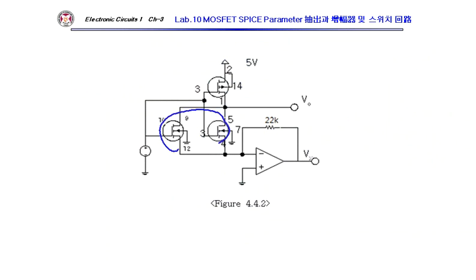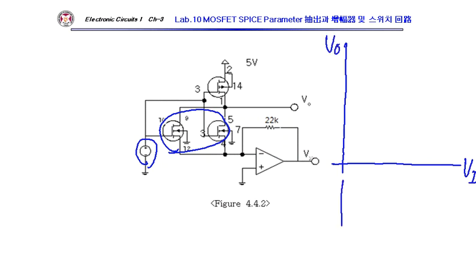Yeah, this is increasing the PMOS part twice. So before that, see, what's the large signal characteristic? Okay, large signal characteristic, VI versus VO. So if I change VI from 0 to 5 volts here, you can watch this one in here.